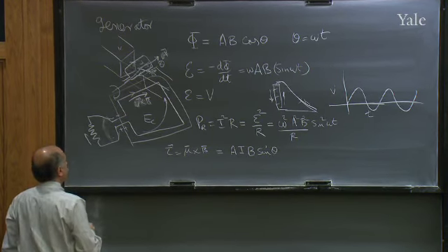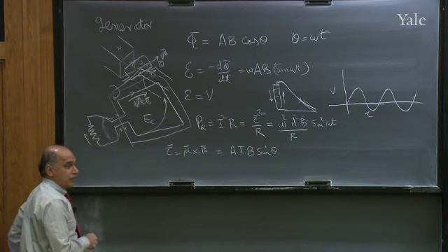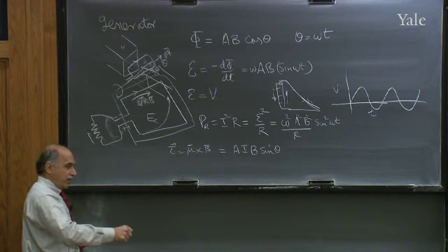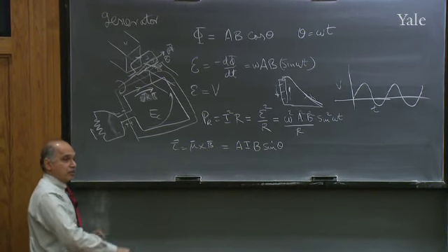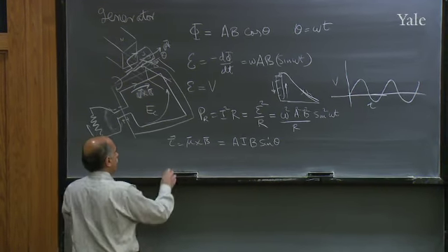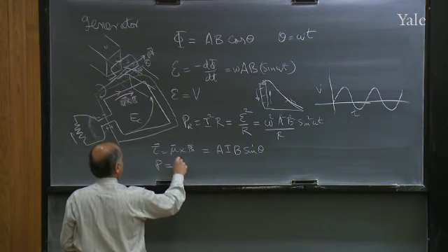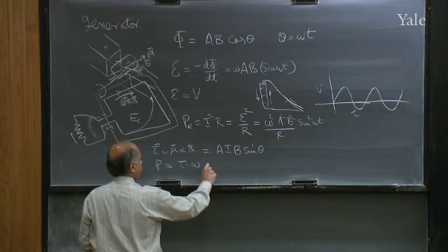So that's the torque that you got to fight. So you will have to apply mechanical force to turn that. If you're turning the crank by hand, the minute you put a load, you will find it's hard to turn it. And the power, just like power is force times velocity, for rotational motion is torque times angular velocity.